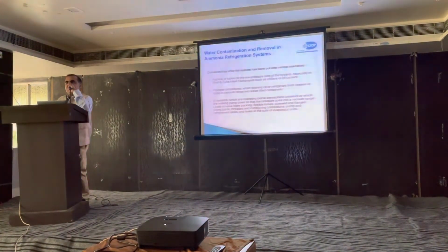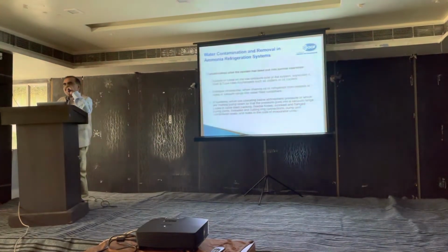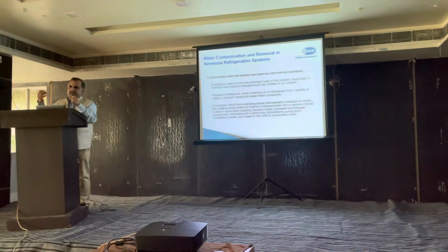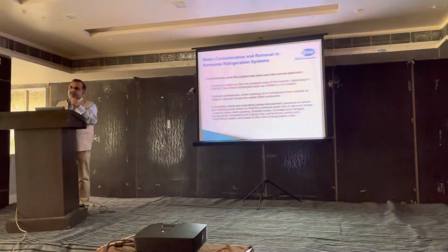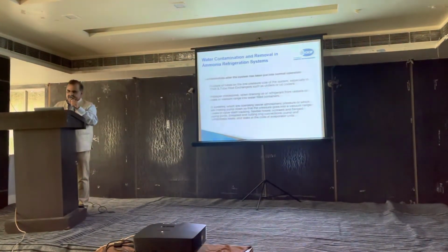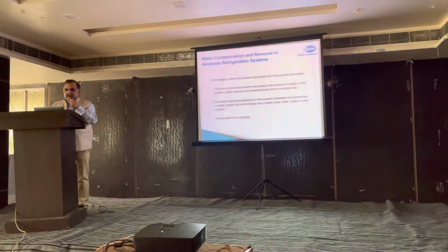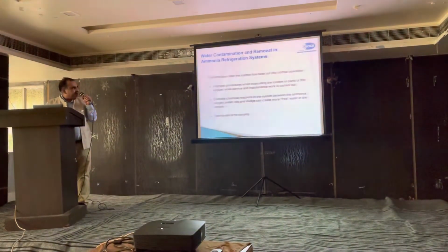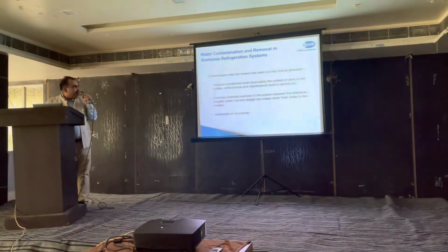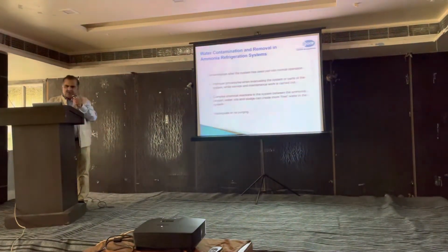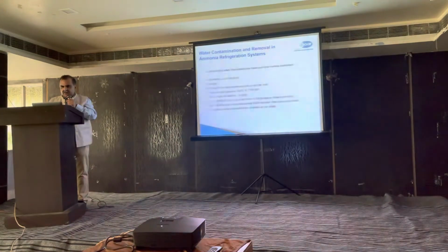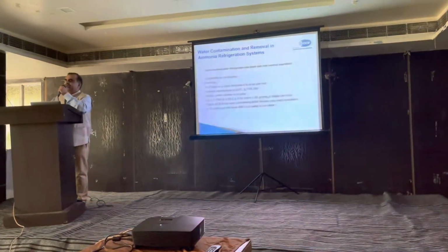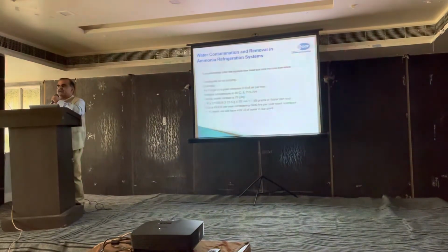When the plant is running in vacuum, certain moisture from the air will also get into it. Even though your purger will separate out the air, the water will remain in the system. The water will continue to remain in the system. Let me tell you how the air purger actually gives us an indication of water getting into the system.